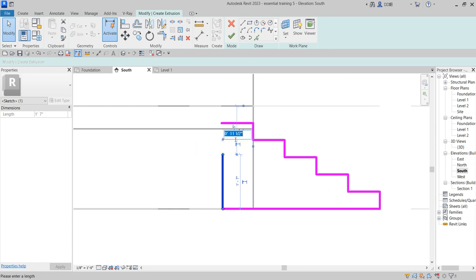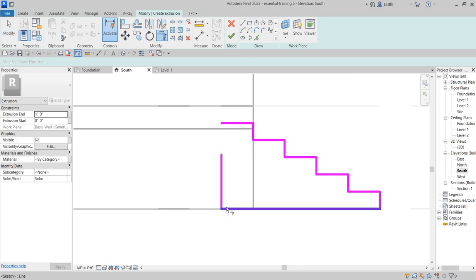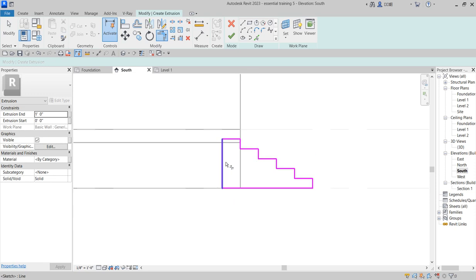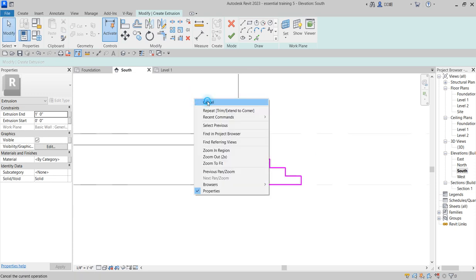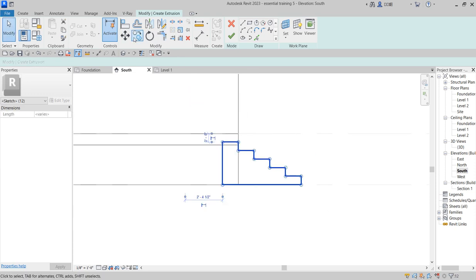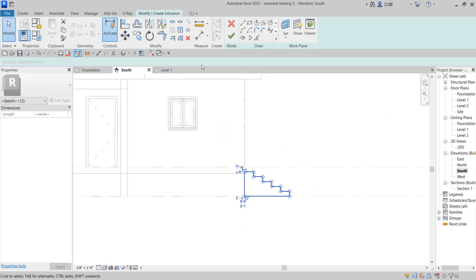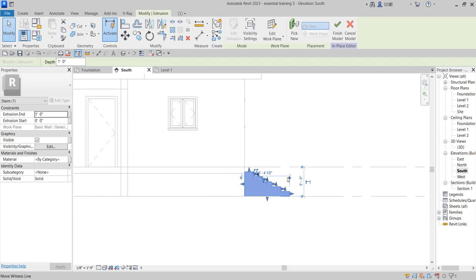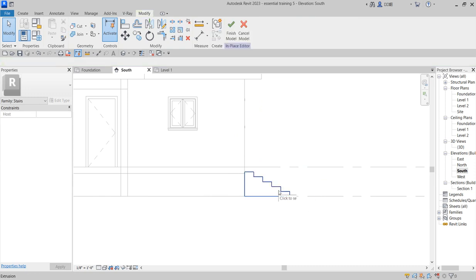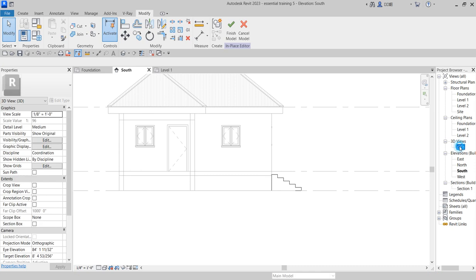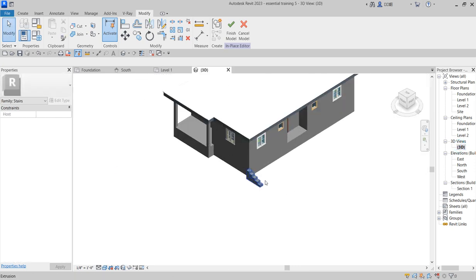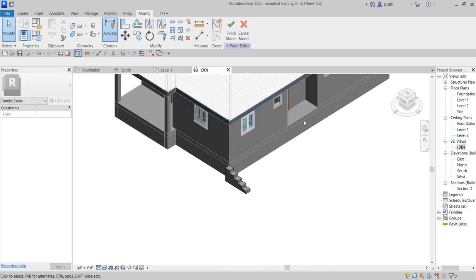On this, just type 1. Good. So it snaps to that pole. Then you remove it and take it up to the outside. When you click finish now, the staircase is generated in this way. So go to 3D and see what you have done. So here it is in 3D. You are going to use it for this stair at the entrance to the kitchen.